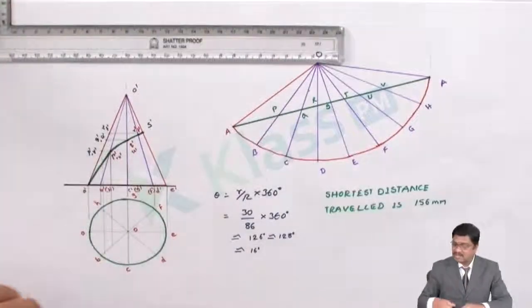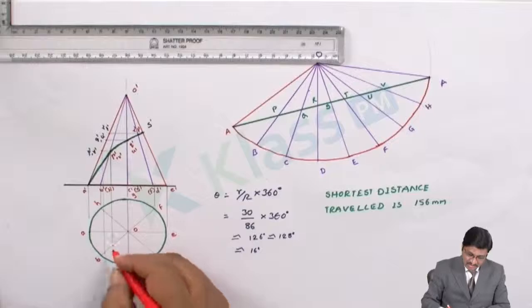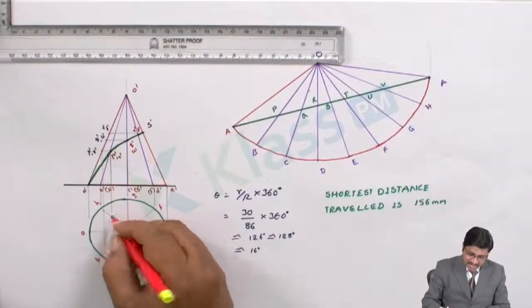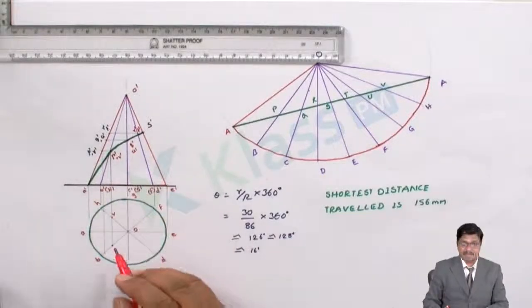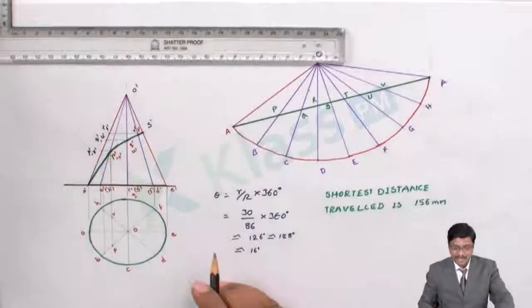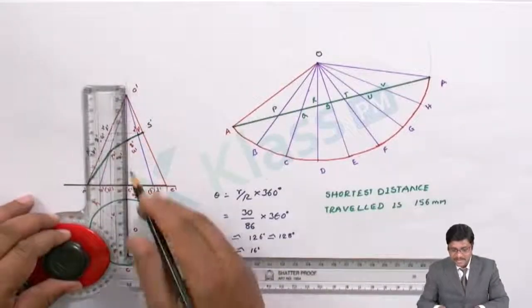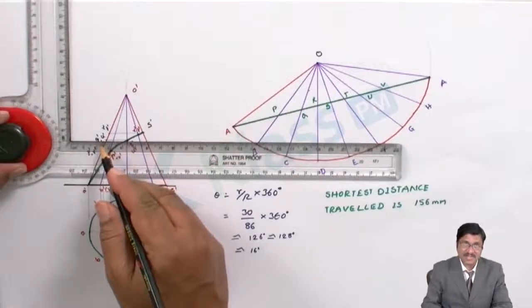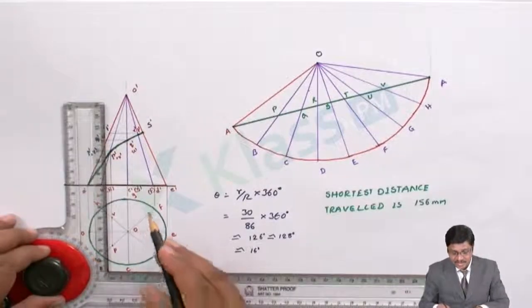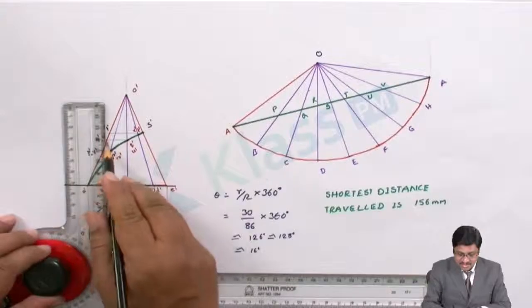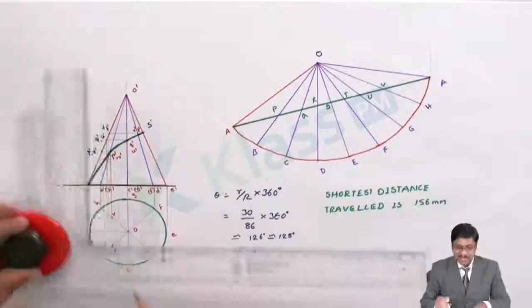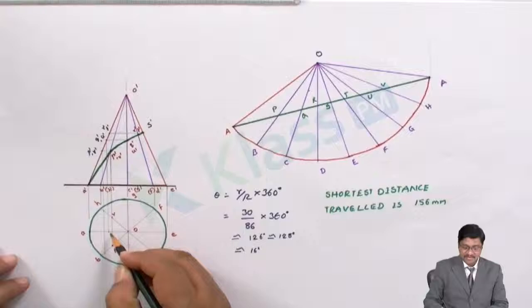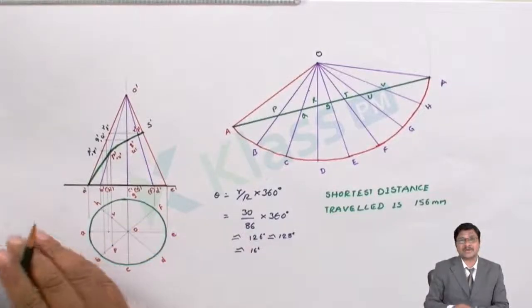So on OB, which points are we having? The P point, and behind it the point V. Similarly, Q and U. So what happens while drawing Q and U? It is merging along the generator. In such a case, I have to transfer from the nearest true reference, from the true reference onto the respective temporary generator on OE. From the OA, it has to be brought back onto the proper position.